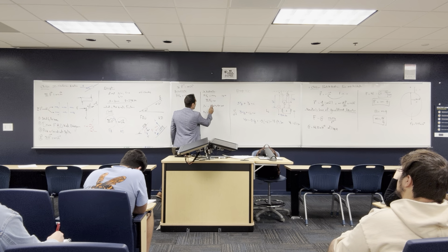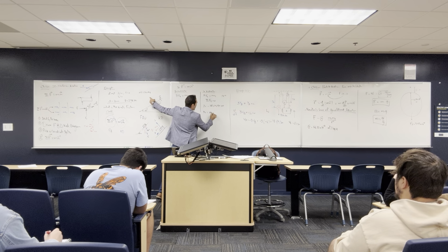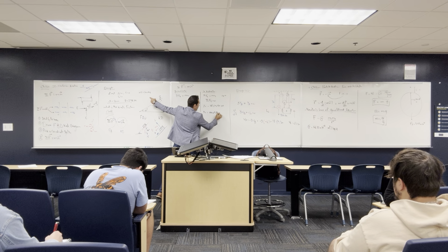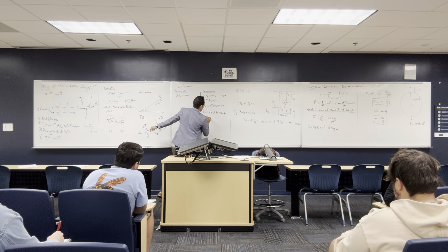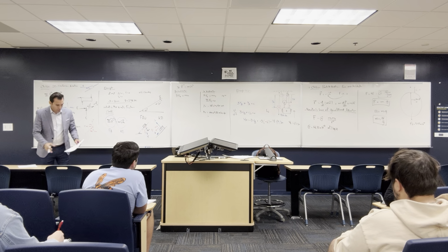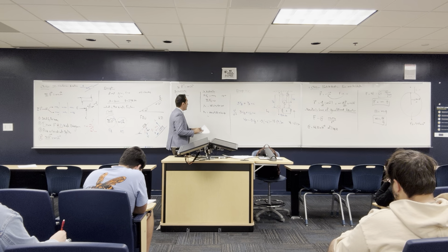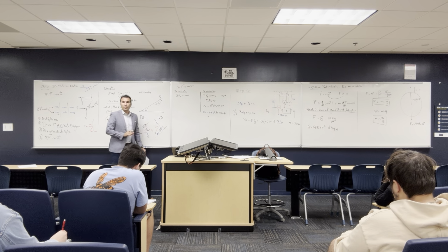Alright, so right now I can get what the normal is equal to. The normal is going to be equal to W cosine 40, and W I know from the mass, so this is going to be 100 multiplied by 9.81 multiplied by cosine 40. Do you guys have a calculator to calculate this quantity? Because I didn't calculate it here. Anyway. Does anybody have a calculator?